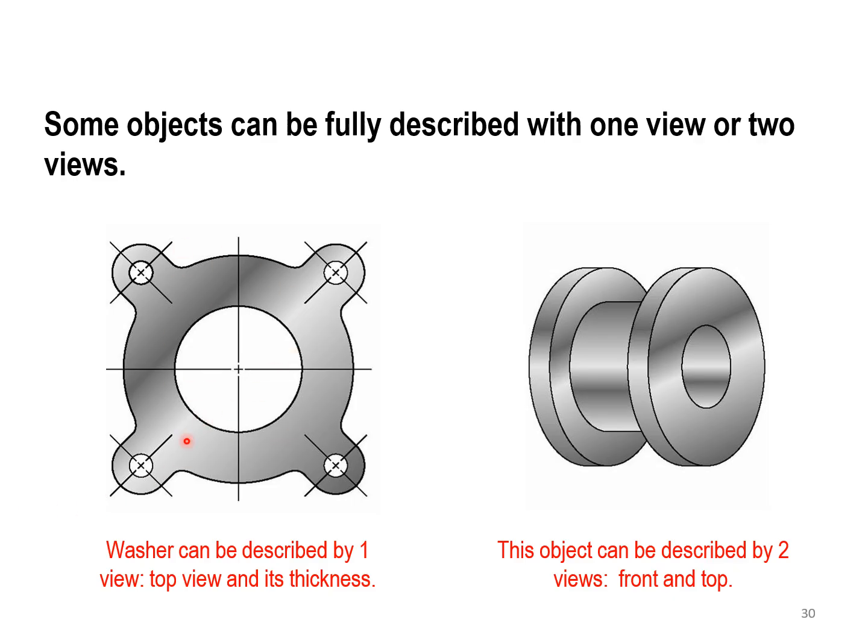That's what I need to cut the washer, and I'm going to give it different thicknesses. It can be 1 millimeter, it can be 5 millimeters. The other object is going to be the roller. I can describe it with two views, which are going to be the top and the side view, or we call it the front view. From the side, the front view is going to look like an I letter, and from the top it is going to tell me that there is a hole in the middle, and I know what the diameters are.